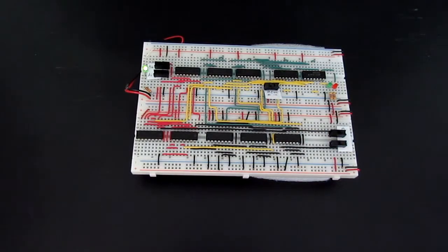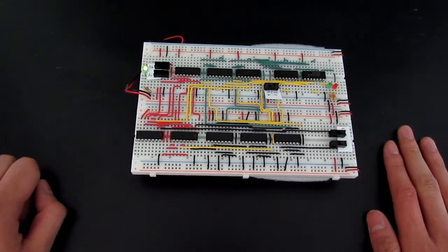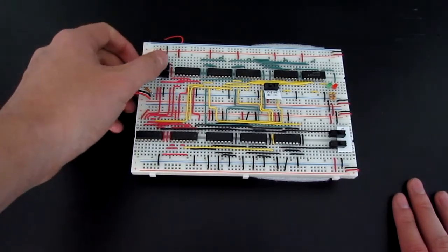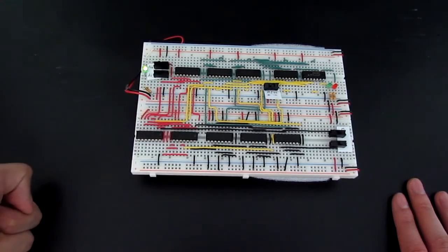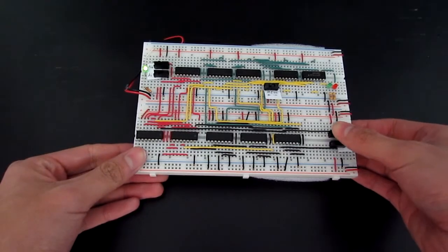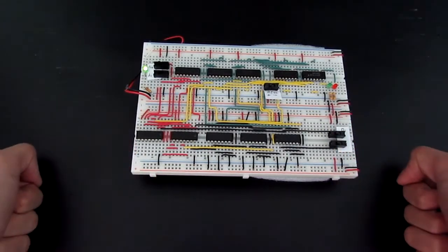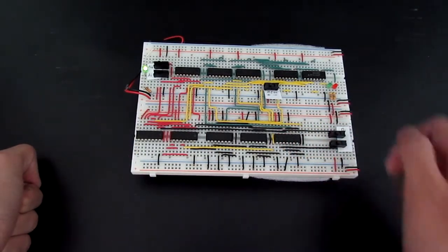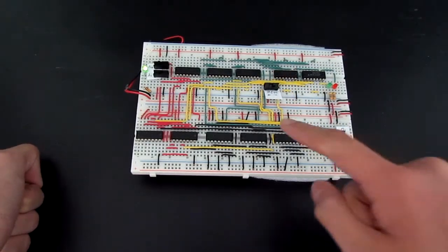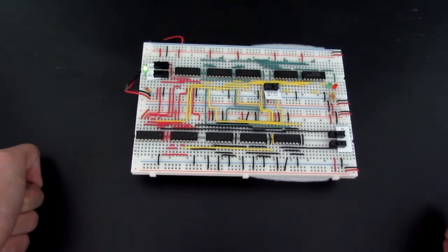Let's try saving the number 3 into the 3rd memory cell on the real circuit. We first must turn on the circuit, and then set address leads to 1, 1. Then, we set the data switches to 3, once again, 1, 1. Now, to save it into the memory cell, we have to set the circuit into write mode. It is now saved into this memory slot 3.